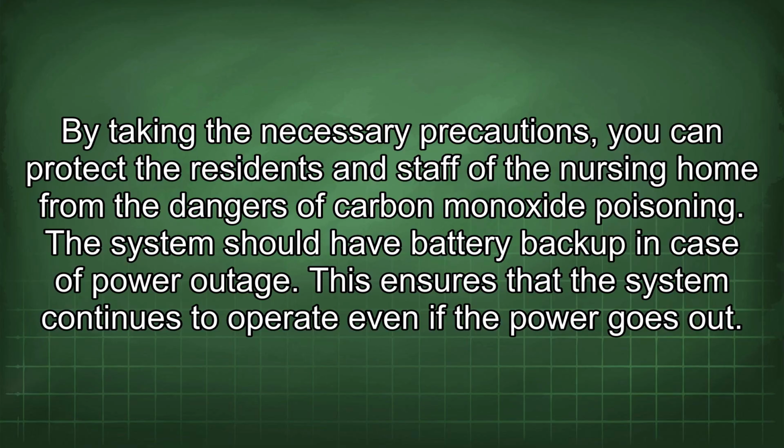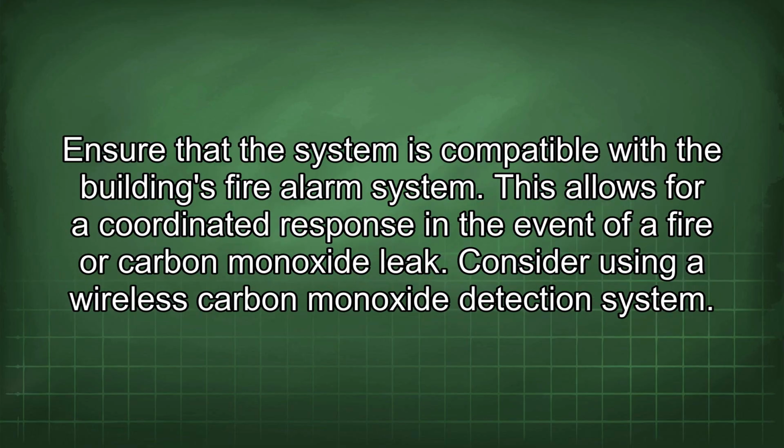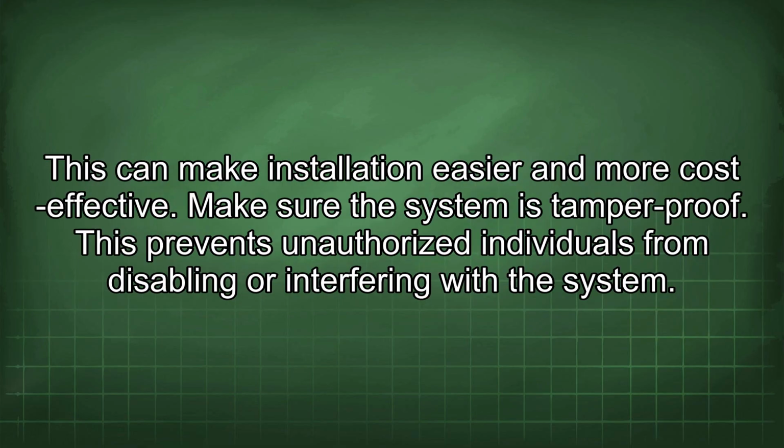This ensures that the system continues to operate even if the power goes out. Ensure that the system is compatible with the building's fire alarm system. This allows for a coordinated response in the event of a fire or carbon monoxide leak. Consider using a wireless carbon monoxide detection system. This can make installation easier and more cost-effective.